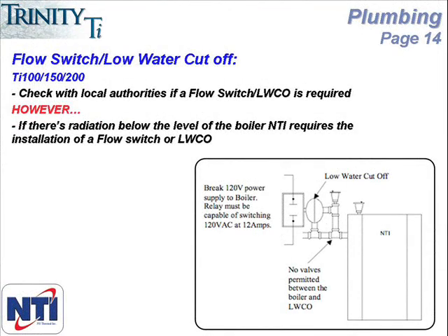Many local codes require the use of a low water cutoff or flow switch. If local codes don't dictate the requirement of such a limit, NTI requires the use of a low water cutoff whenever there's radiation below the level of the boiler. However, it is considered good practice to include a low water cutoff on all installations regardless of code.